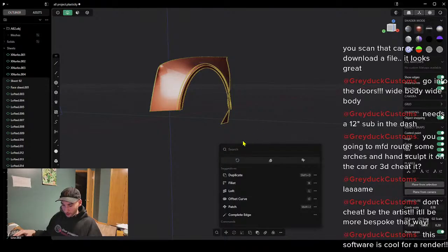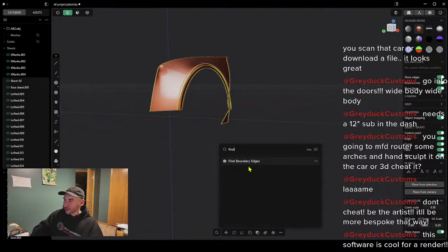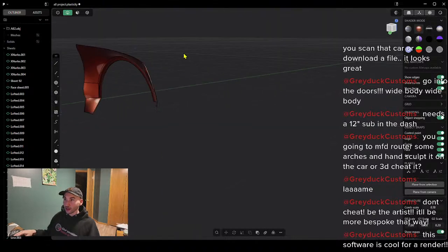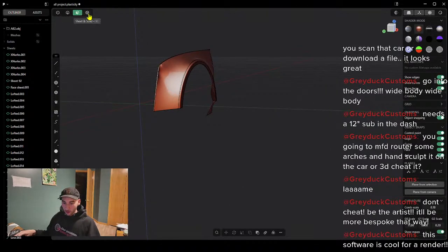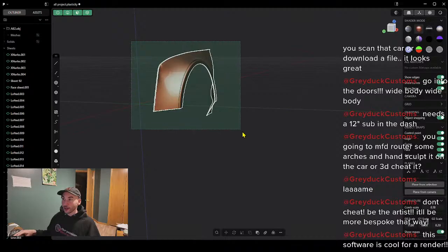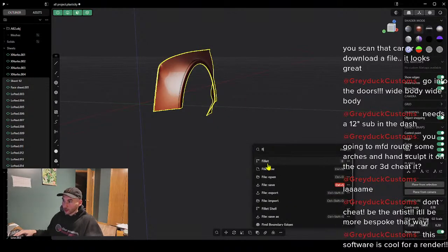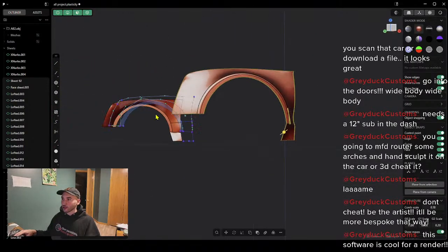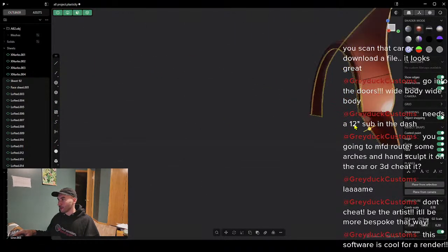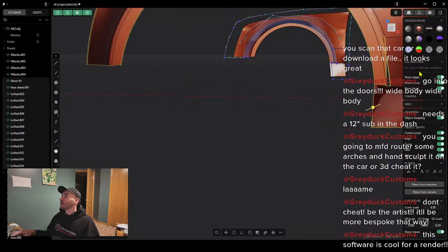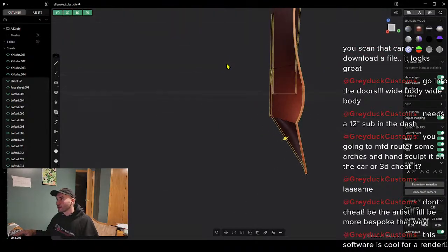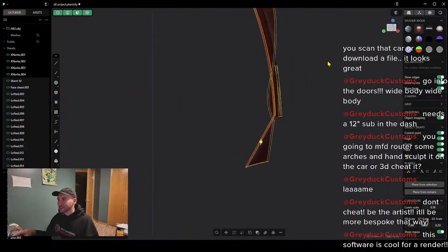So we'll go ahead and I think it was the fine boundary edges, and we tried this last time, but we weren't getting any prompts to come up. But now we hit it. I think maybe we have to have all these selected, edges, and all that, and then hit fine boundary edges. I think that might be the key. There we go. Okay. Then I believe it'll show us or kind of highlight where the issues are. So something ain't happy in here. And you can see it's like every edge is an issue on this one actually.